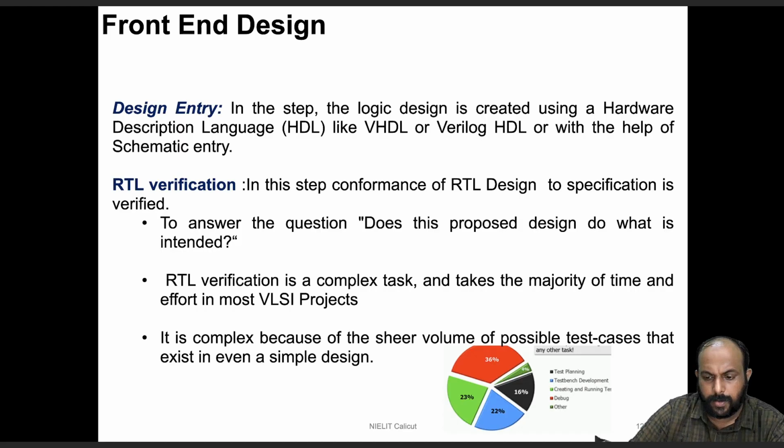Other tasks of the verification engineer include planning the test cases, developing a test bench, creating and running the tests using the processes of regressions, and documentation and so on. RTL verification altogether is a very complex task and a major time consuming task.